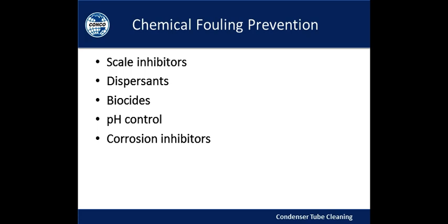The most important thing is to have the right strategy for the right cooling water condition. The water treatment program typically will not eliminate the need to clean the condenser. And while the company might be spending a significant amount of money in the water treatment program, it should also be accepted that the tubes will foul and they will need to be cleaned.